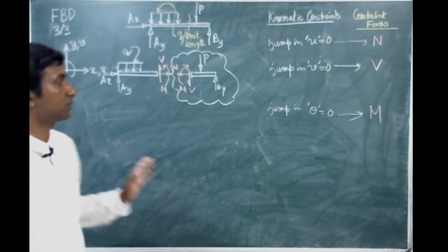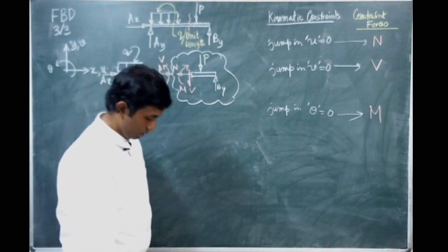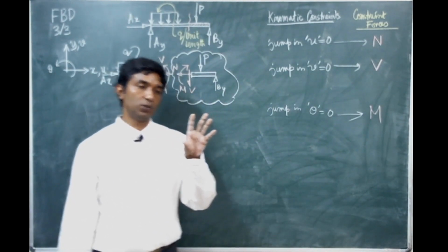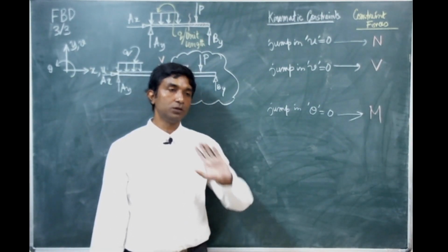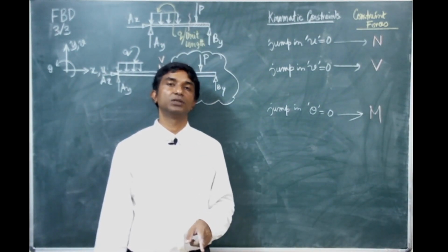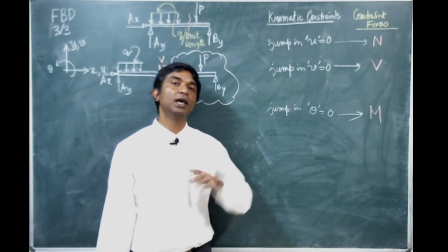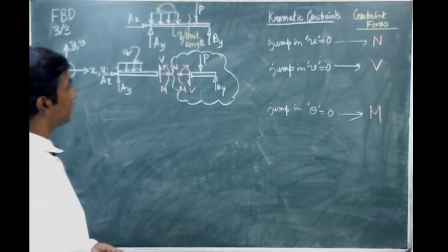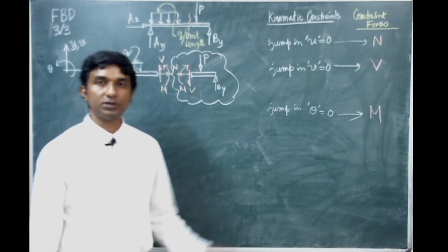So 3 kinematic constraints are identified, 3 constraining forces we have supplied. Okay. So you have to remember the rule. First of all, the portion which you are considering, you keep that, and other portions you delete. Okay. So at the contact faces, you supply the statically equivalent forces. For that, you need a proper understanding to identify the kinematic constraints, and you supply the conjugate forces. So I think I can stop with this, and we shall move to the next topic.